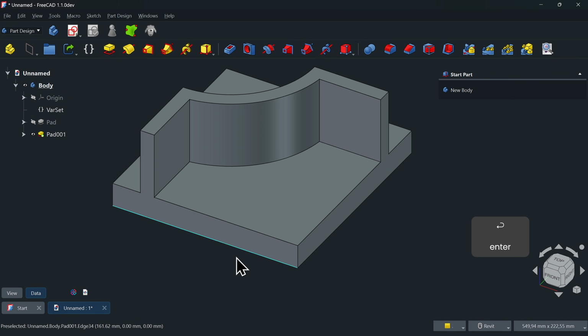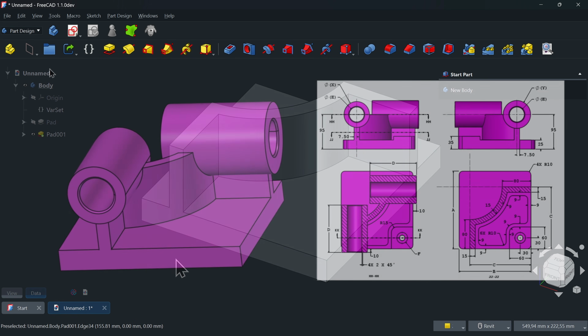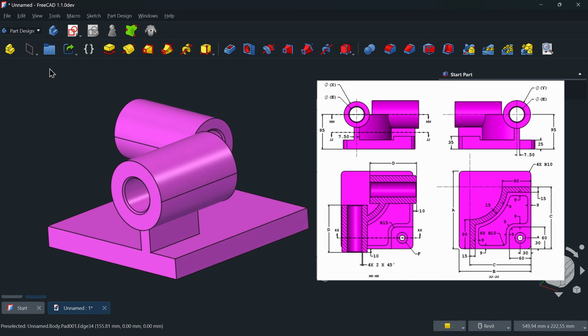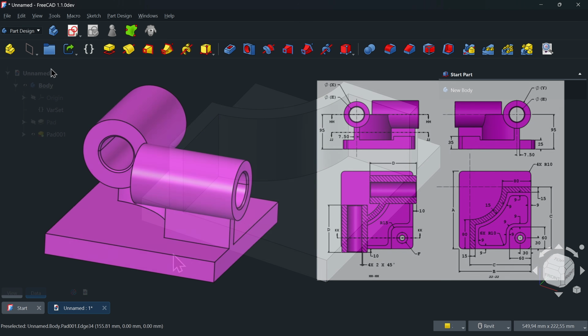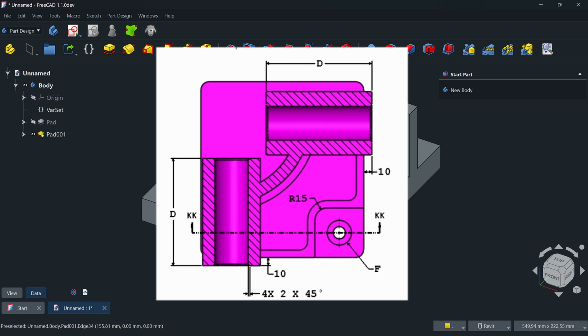At this point, we could go in a few different directions. Either model the 2 cylinders or the whole placement. Here we're going to start with the 2 cylinders. On the drawing we can see that the 2 cylinders are offset by 10 mm from the edge of the part and their length corresponds to variable d. So to create this, we'll